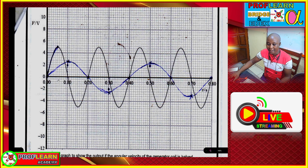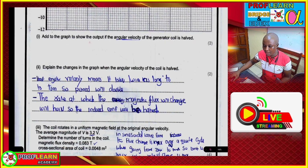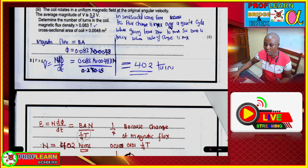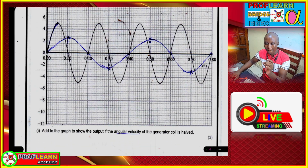So always the time you are using for the change of magnetic flux linkage, guys, is going to be a quarter of a period. That's why you can see I'm having the periodic time times 0.25, a quarter, because the change of magnetic flux is happening between 0 and this middle point. So a quarter of a period.